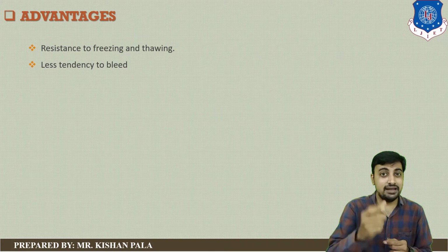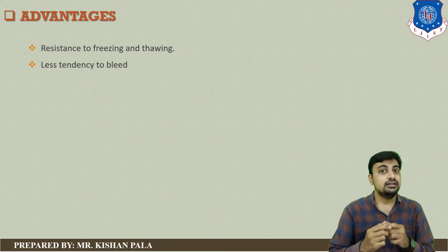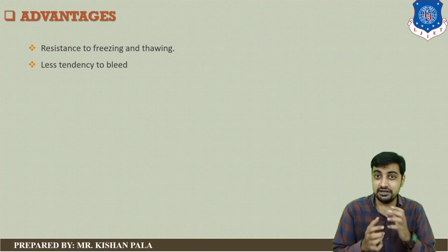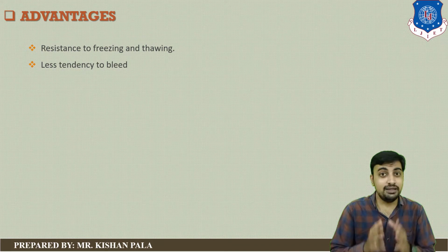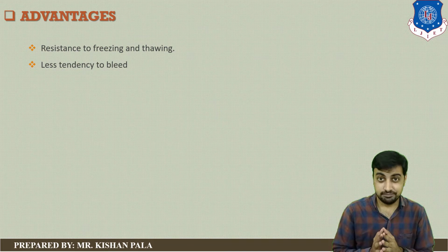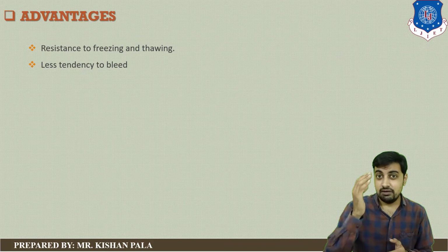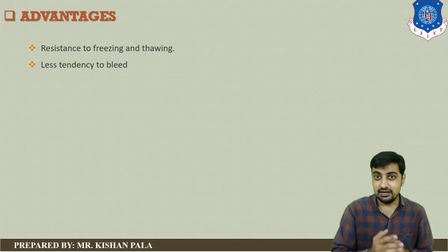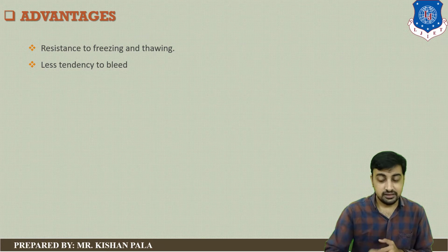This is beneficial for the fresh property of the concrete mass, and with the increase in workability, there will be less chance of bleeding of the concrete mass, because bleeding really affects the fresh property, hardened property, and the durability of the concrete mass.